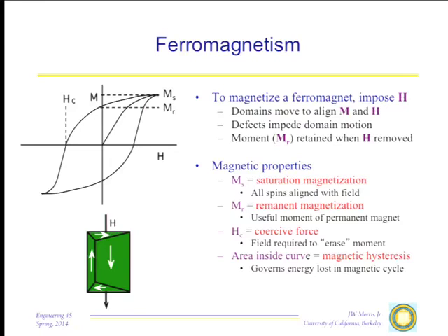Why is there remnant magnetization? Well, in order to get back toward the initial configuration, these magnetic domains have to form and grow again. But now they're growing, they're not being pushed by the magnetic field. They are moving spontaneously under whatever thermal forces are available. And just about anything there is in the microstructure, any non-magnetic solute, any defect like dislocations, grain boundaries, various other such things, will interact with these domain boundaries and make it difficult for them to move. So they rather quickly, in some cases, get pinned. And where they are pinned establishes what the remnant magnetization is.